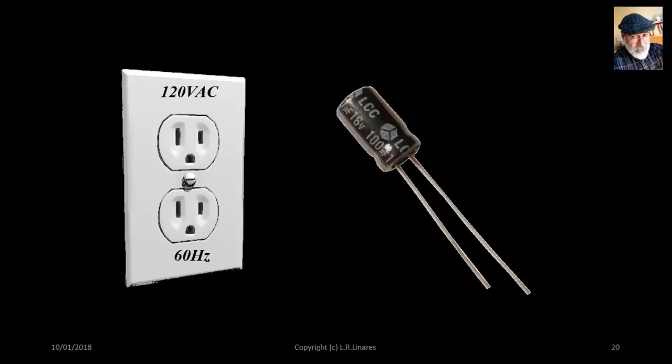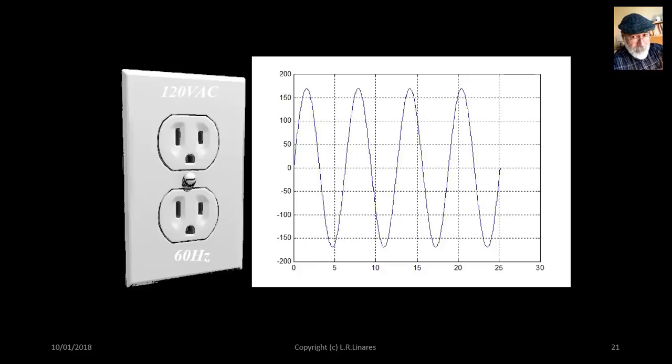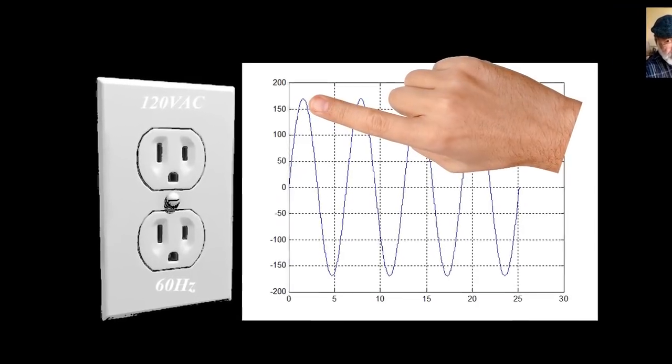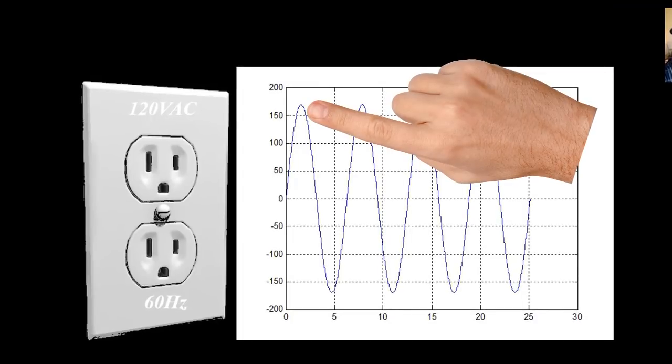When we go to the power outlet on the wall, and we know the voltage is 120, that 120 actually is the RMS value of the voltage there. It's 60 Hz, 120 volts RMS. If that voltage is sinusoidal, it reaches a peak, a maximum value, of root 2 times 120, that is about 170 volts on the peak. In the laboratory, multimeters these days measure volts and amps.